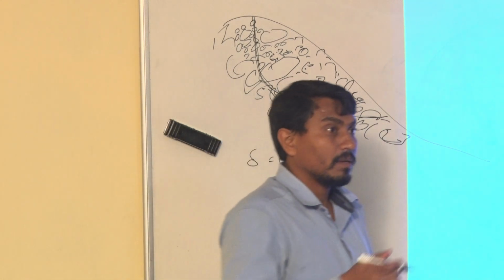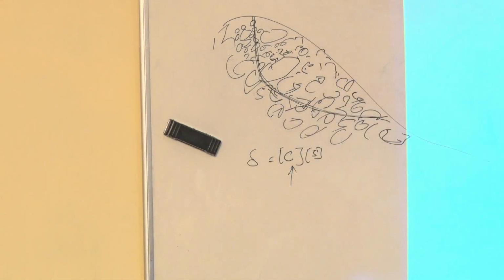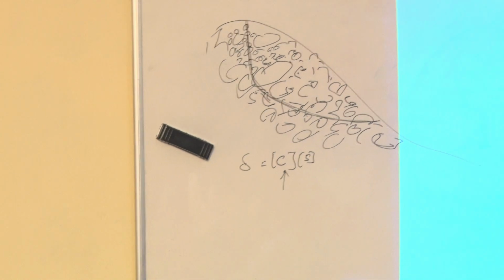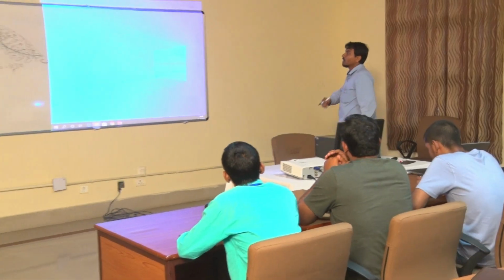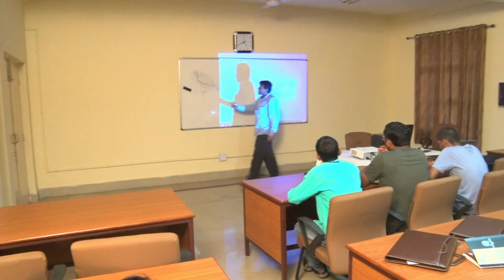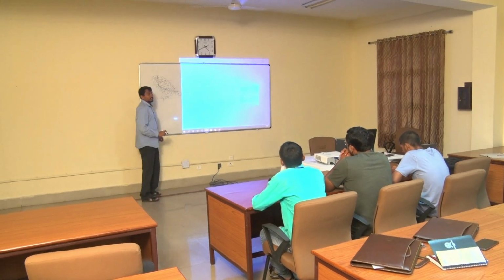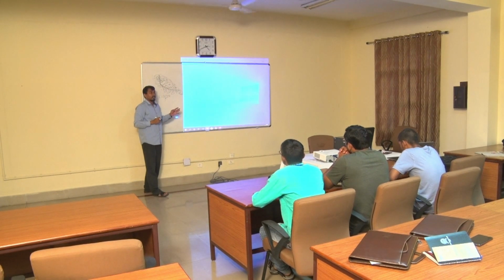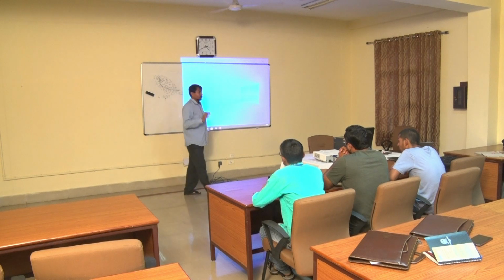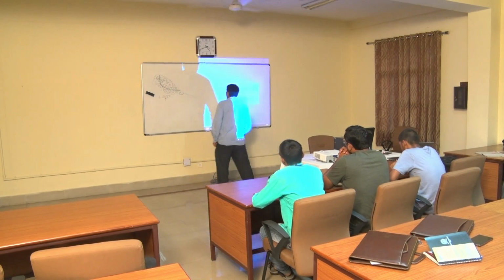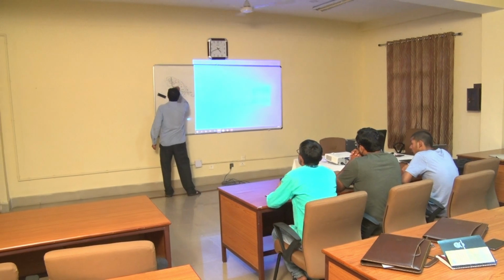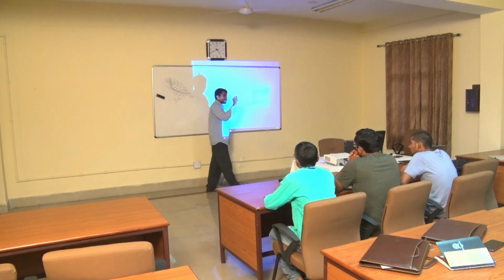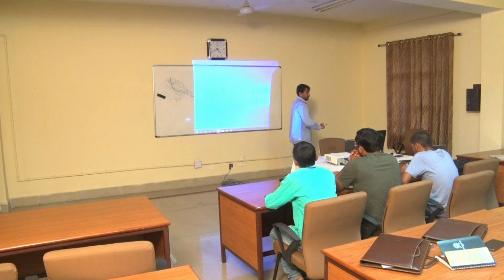How are we telling that? Because from today's laboratory test, you have already seen that if there is a movement along two planes, there is some amount of rupture developed. So from the failure plane, we can predict which kind of movement occurred, whether that movement has broken the block or not. Generally, it is not. The answer is no. So the general failure pattern is along the weak material, that is fragmented, very loose material and soil.